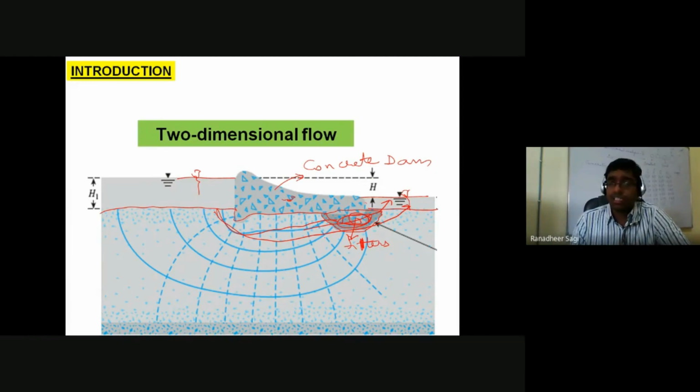Now, in such cases, after some point of time, the size of the interconnected void path keeps increasing, and you are going to see a large void cross-sectional shape getting formed similar to a pipe inside your ground or inside your soil strata, because of the escaping of your soil grains from that particular soil medium along with the seepage happening through the soil strata.